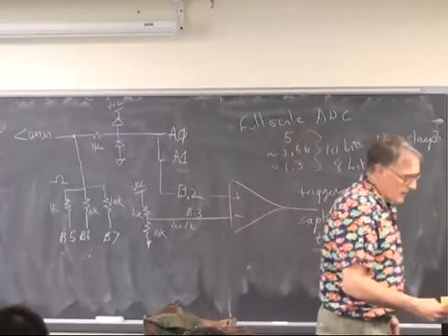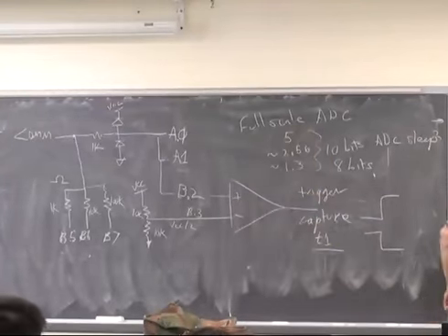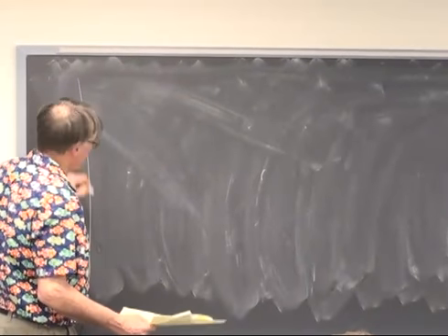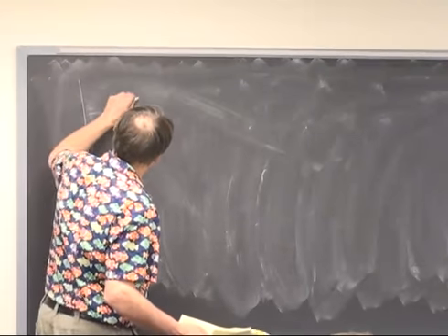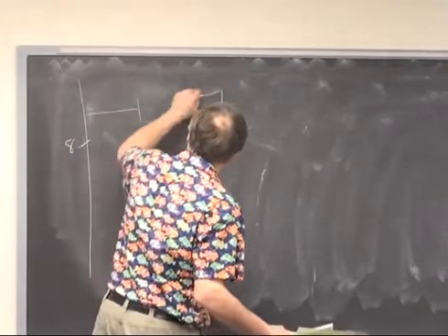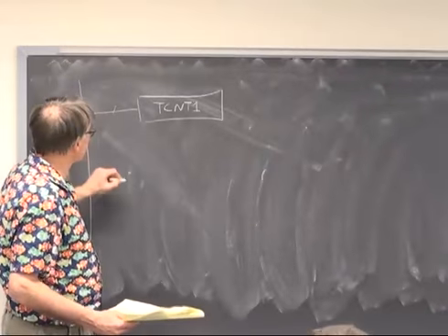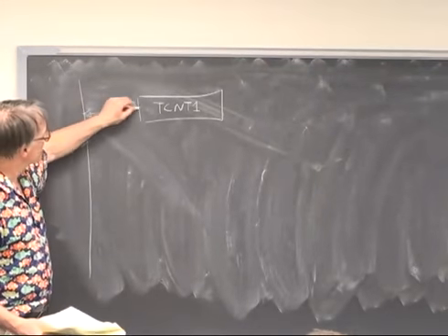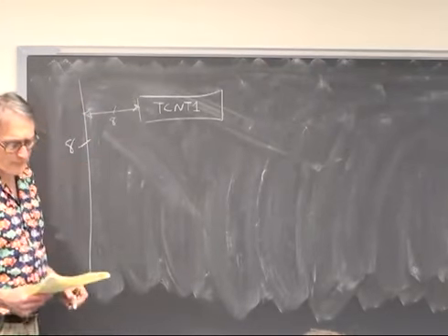So let's build a diagram of timer 1. It's pretty similar to timer 0, but there's the usual 8-bit bus that feeds everything, and then there's TCNT1, name of the register, but it's a 16-bit register with an 8-bit connection to the bus. Oh man, what does this mean?